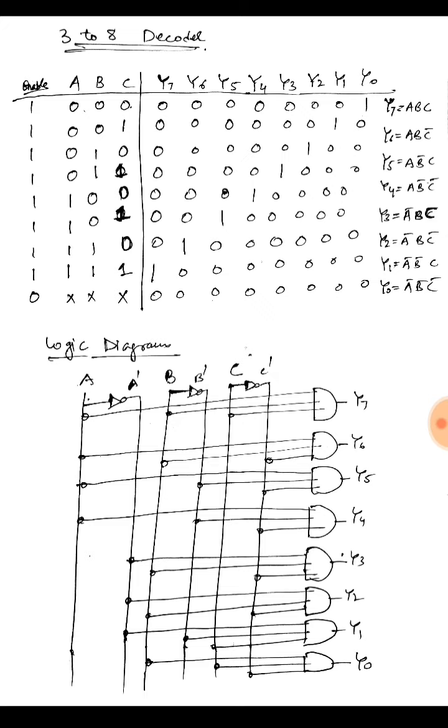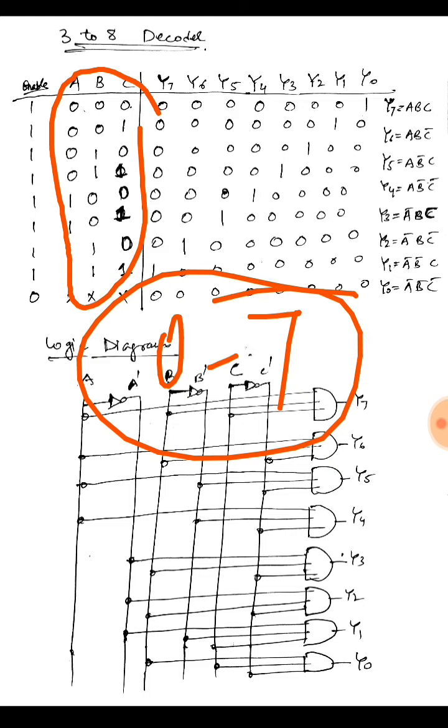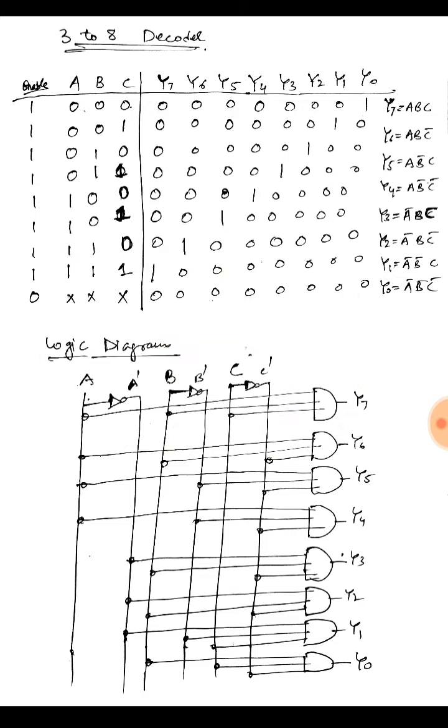Okay. So if we have a 3:8 decoder, that is at the input I have 3 digits A, B, C. Using these 3 digits I can represent 0 to 7 decimal numbers. If all of them are 0 0 0, then output Y0 would be high. If I have a combination of digits like 0 0 1, then Y1 would be high.